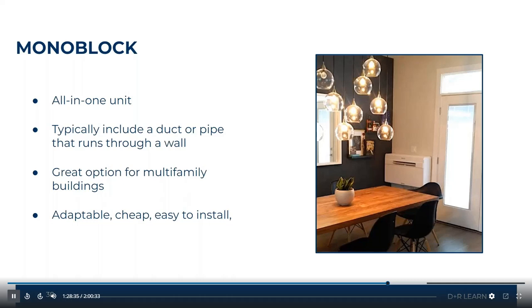On your mini split system, because those systems are working DX, meaning direct expansion, so it's utilizing refrigerant as the direct medium for heat exchange, that system is going to require a different means of fresh air being introduced into that system.